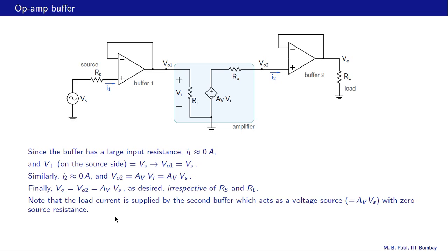So this is how a buffer can be used. Whenever we are concerned about loading effects, we can insert a buffer, and that essentially eliminates the loading effects.